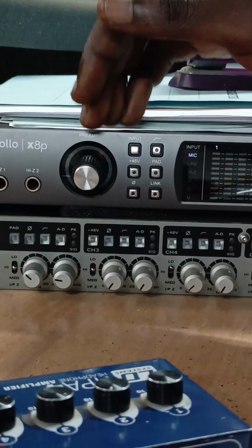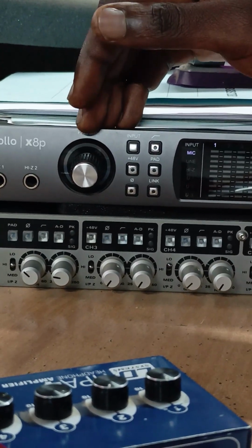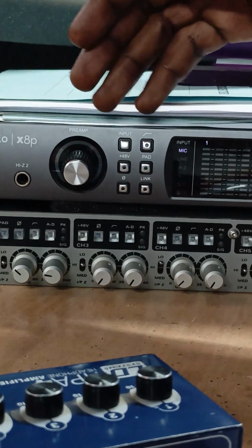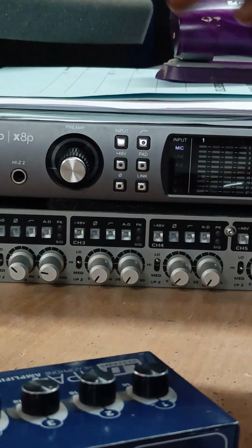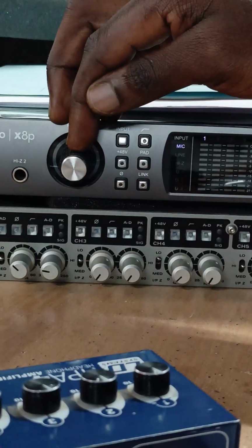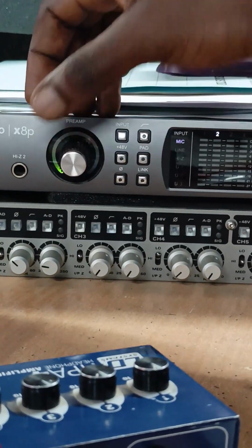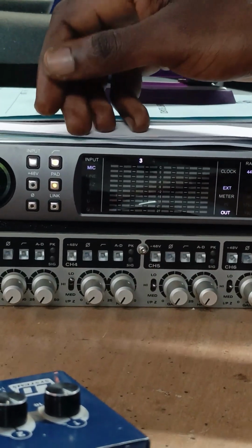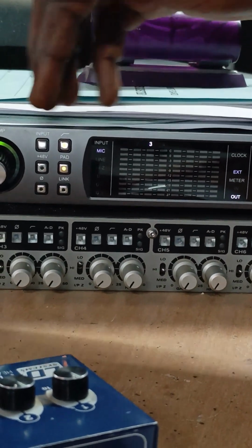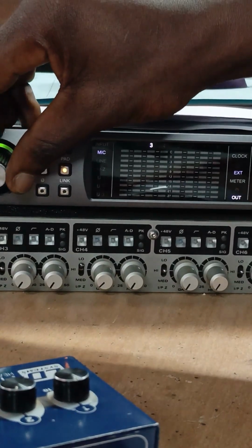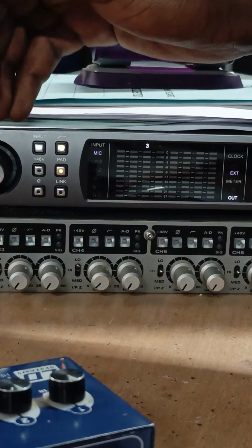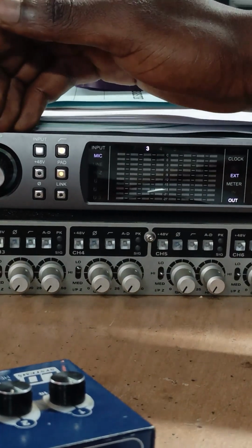Of course, gain staging happens before you record. So before recording, you have to gain stage all your channels, as I said, or 8 channels. And this gain knob, again, can be used to select channels. As you can see here, as I'm pressing it, it is moving. So to each channel I go on, using this gain knob, we can change the amount of signal which is allowed to be recorded.